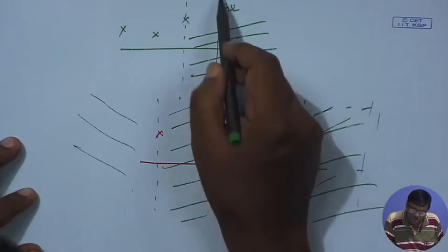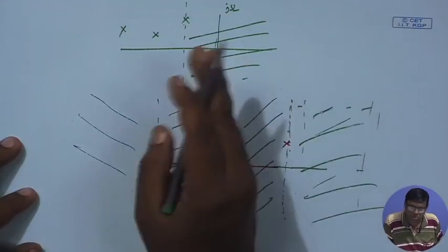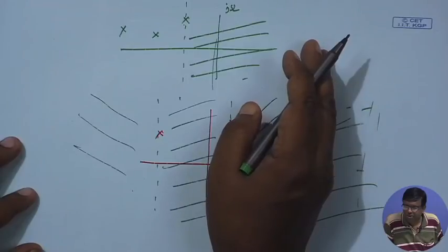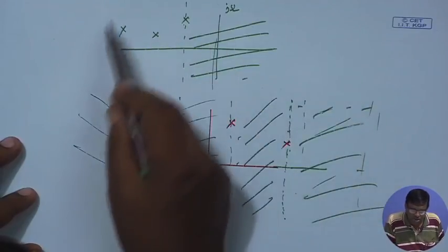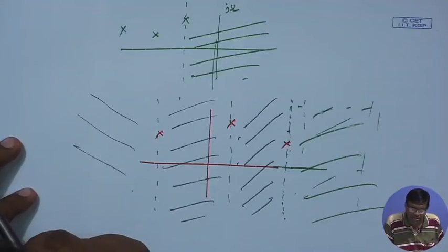So, this zone contains j omega axis and it is going to the right side of a vertical line. So, it will be both causal and stable. So, that means all the poles must be on the left hand side of the j omega axis. That side is called LHP, left half plane in the S plane.